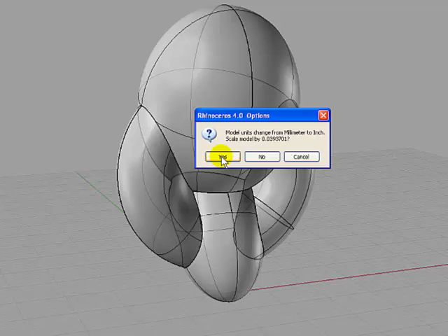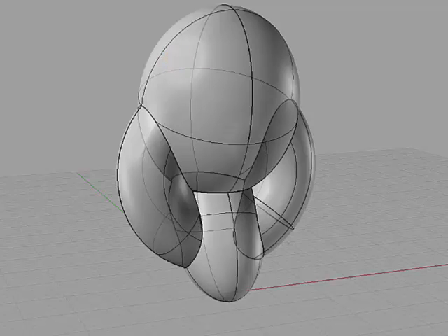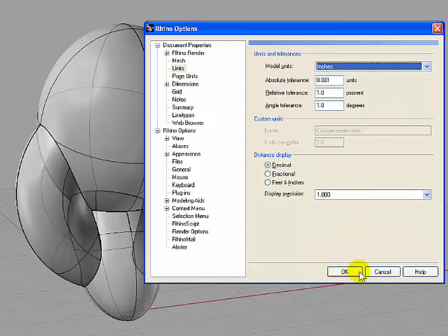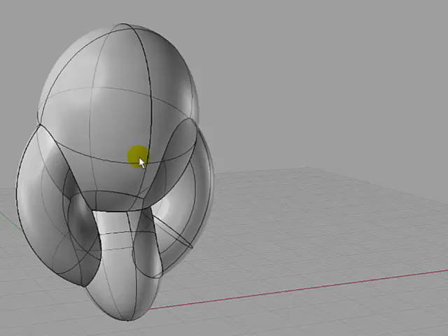And when you do that, what happens is that the scale of your model shrinks. And that's usually not what you want it to do. So I'm going to hit Control Z, and I'm going to come back and convert millimeters to inches. If you want to maintain your model as you built it or as you anticipate that it will be in inches, click on No, and that just maintains the size, and it converts the size that it was in millimeters straight to those same units in inches, so that if it was 25 in millimeters before you created it, it'll automatically make it 25 inches, and that's very helpful.